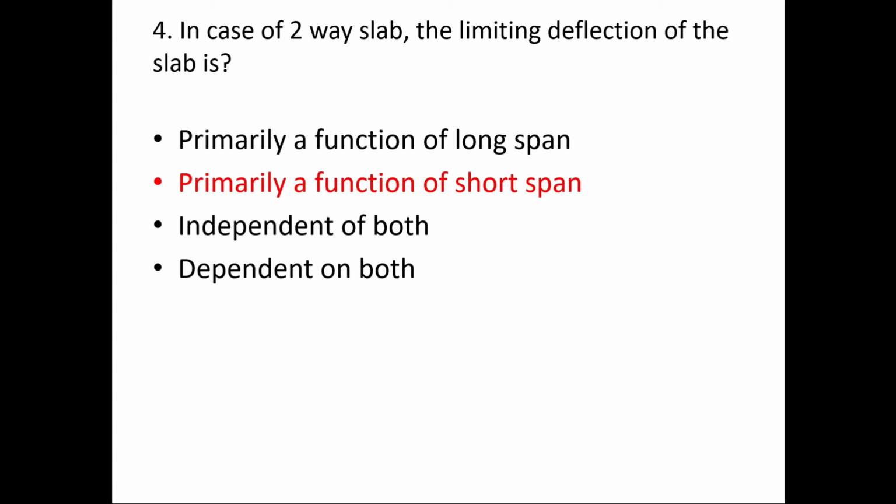For mild steel in the simply supported case, the span to depth ratio is 35, and for Fe415 it is 28.